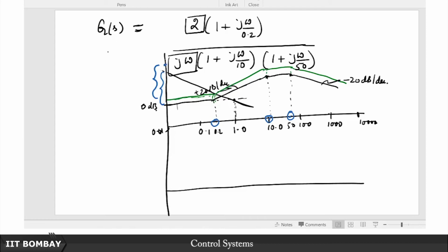Once you have figured out this point, whatever was the length of this, where the integrator was cutting this at whatever frequency you started sketching, you cannot go all the way down to 0, remember, because it is a log scale. So you are starting at some non-zero frequency here. At that non-zero frequency, you see where this line with a slope of minus 20 dB per decade and passing through 1, 0 cuts your y axis. This y axis may vary from person to person. I might have gone all the way down to 0.001, but wherever it is, at some point we have the y axis drawn.